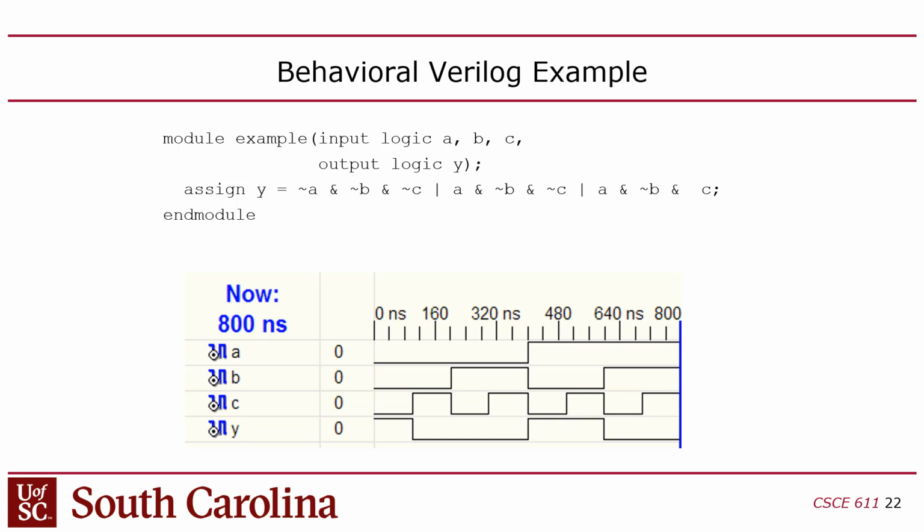So notice that when the C value changed state from 0 to 1, it immediately dropped the Y, right? Now you might say, okay, that's fine, but who is controlling A, B, and C? Where's that coming from? Is that automatic? No, it's not. You have a choice. You can either write a test module that sets those inputs, or you can do it from the simulator itself. You can use force commands in a language called Tcl to set those values. Those are your two options.